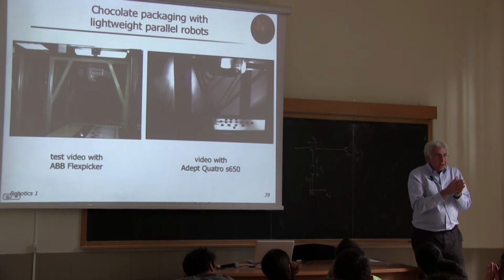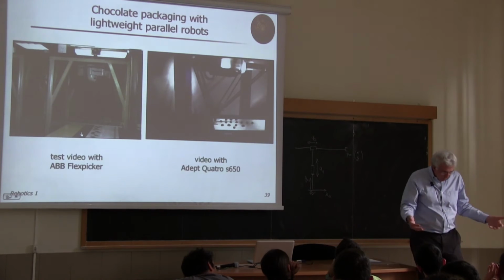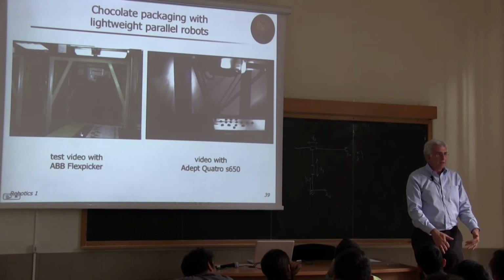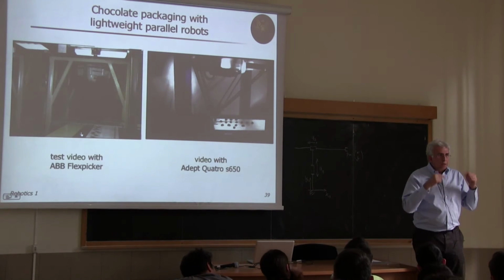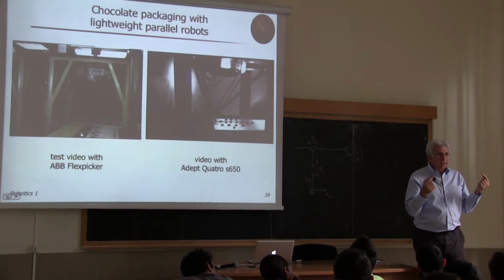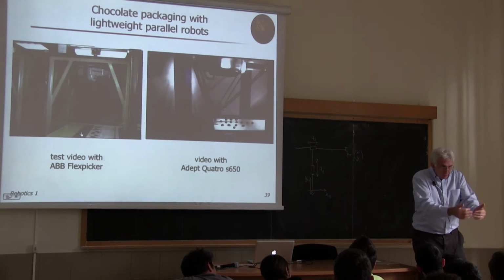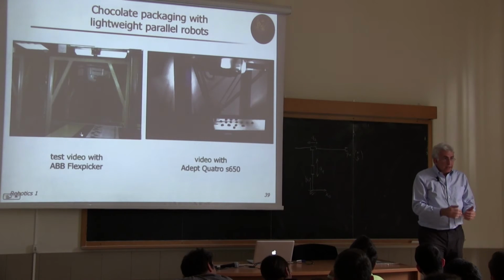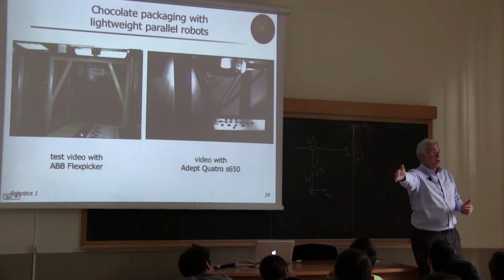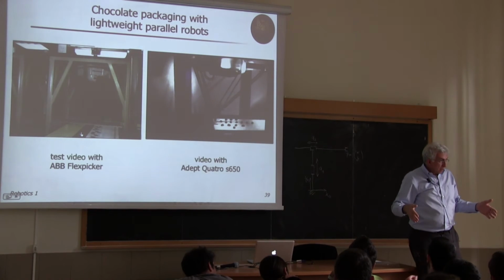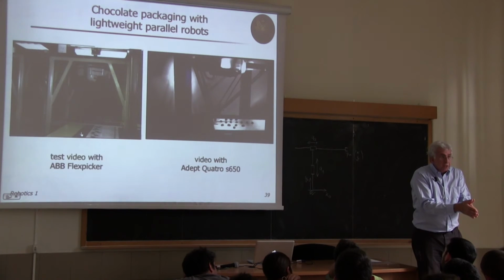And if I have a limited amount of time, because there are many objects coming, and I should avoid letting them fall down, namely, I should pick them all, I should also implement an algorithmic strategy that tells which object I should take first, probably the most critical one, taking into account that I need more time to pick an object which is on the side of the conveyor belt than one which is in the middle.